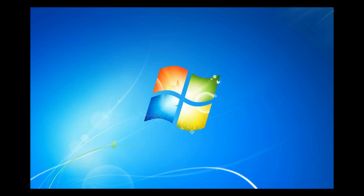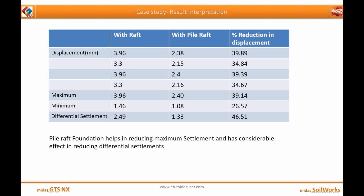So there are a few queries like how to decide the mesh sizes. As you can see, we have imported the building model, so we should consider the mesh size such that there is proper nodal connection between the imported beam node and the mesh of your model. So for this I have chosen that criterion, that there should be proper nodal connectivity between the nodes of the imported model and the raft foundation which you have created.